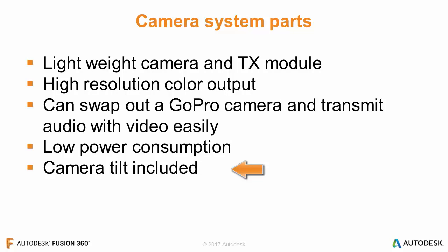you can buy individual servos, you can buy specific cameras and transmitters, and you can pick and choose which components you want. You can very easily get away with using a GoPro that you have because we're planning our build so that we have enough capacity to lift a GoPro or additional equipment as needed. So that might be a great way to get a first-person view by using a fixed GoPro without including the tilt module, plug it directly into the transmission.